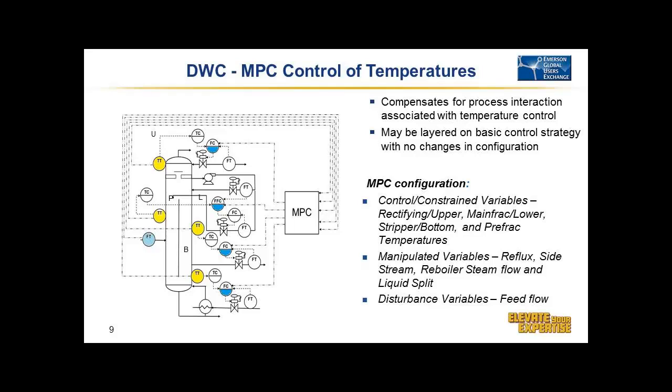And so we can use this as an operating variable, and Willy will show you some of the results from that. Additionally, our B products, you can think of it as a reflux. So we have a total trap tray here. We pull the liquid out, and we can either take some as a product and then reflux some of the B back. So that's another one of our operating parameters that we use in MPC. And so you can see how we've done that. And noted the valves in blue are wireless capabilities.